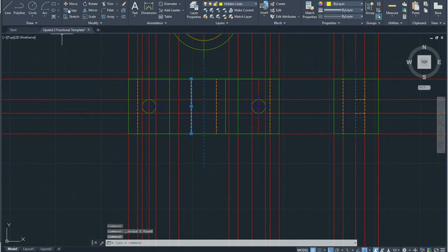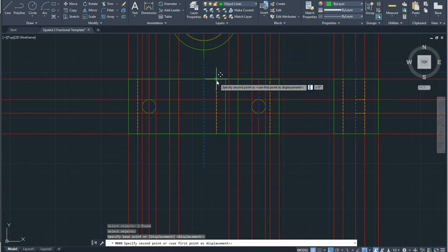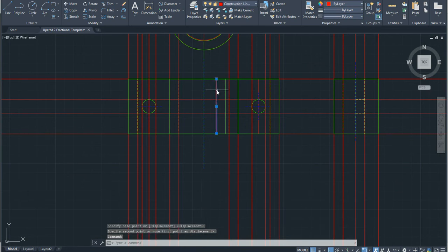Now I do want to move this line on my hidden lines right there. And that way I don't have to change that line. I don't have to change my layer. My layers automatically change. So then I want to move this line here. Enter. Make sure you use your snaps when you're moving things, the way they line directly up. All right. Then you can delete this line here, because that was the original line.